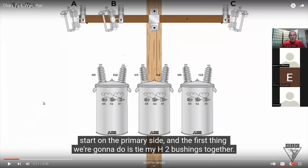They only use 2 of the lugs. I like giving it separation. I like to use X3 and X1. They're using X2 and X1. Under X2, they have AC, and under X1, they've got BD. Still serves the same purpose. They're just using 2 different bushings.